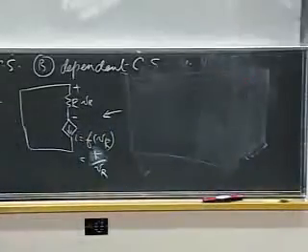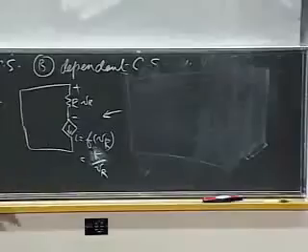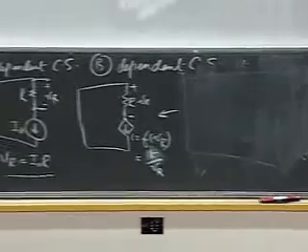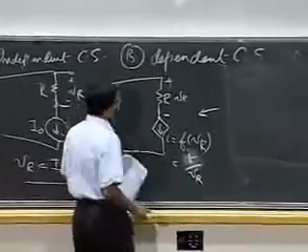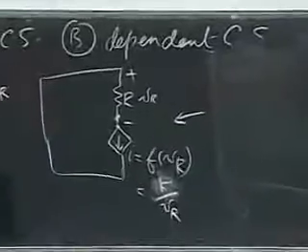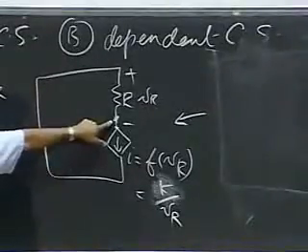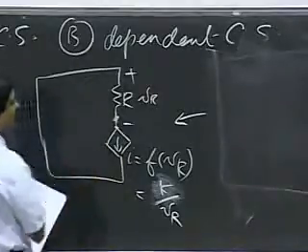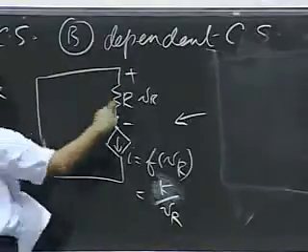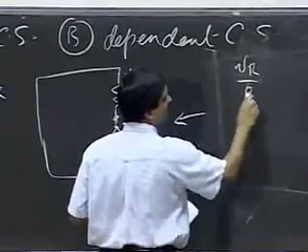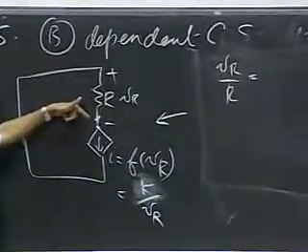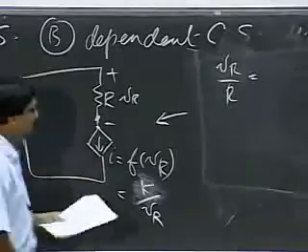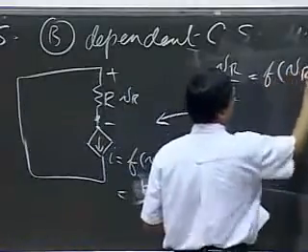Okay, so let's go ahead and analyze this little circuit here and look at what this might give us. Our goal, as before, is to find out the value VR. So in this case, let's apply the node method to this node, and sum the currents going into that node to be 0. The current going down is simply VR divided by R. Okay, and that is equal to the current that is going out of the node, and so that is equal to F of VR.